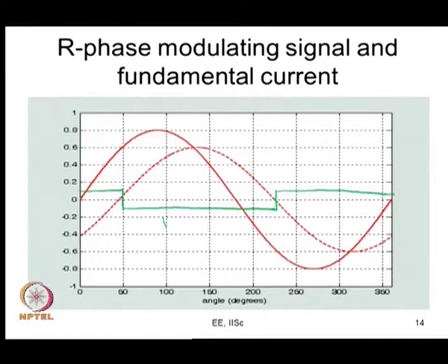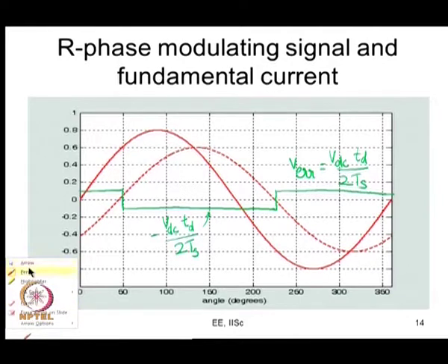Let us do this. So, the error voltage is VDC and that voltage is seen for a duration TD in every carrier cycle, which is 2 Ts. So, that is this voltage level. This is actually minus VDC TD upon 2 Ts. Here you will have VDC times TD upon 2 Ts. So, let us call this V error, the average error voltage, that is the error voltage which has been averaged over every carrier cycle, right. So, this is the kind of error voltage.